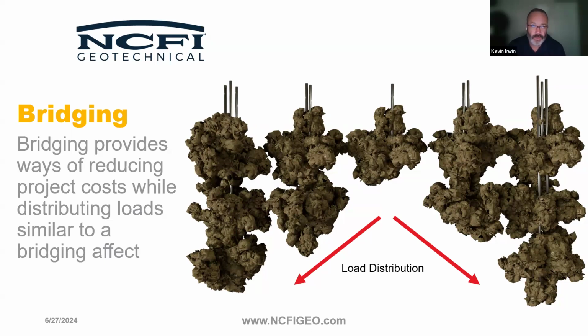I've seen others, and in fact, I myself misunderstood that when I first started with chemical in 2006. So foam will absorb water, right? It's got cells in it. Those cells are made by bubbles that are let off during the chemical reaction, and then the polyols harden around that and give it its structure. We certify we're 90% or better closed cell, depending on which system you're looking at. But if you open those cells up, they're going to absorb water.